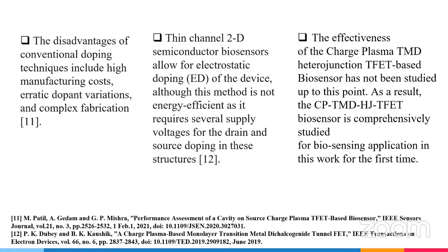We have studied that charged plasma TFET can be easily fabricated, and there is no need for various supplies in the drain and source regions. There is no need for doping like electrostatic doping. So we have applied the charged plasma technique with the TMD and the heterojunction TFET. We have combined the charged plasma TMD with the heterojunction TFET, and we have studied this for biosensing purposes.